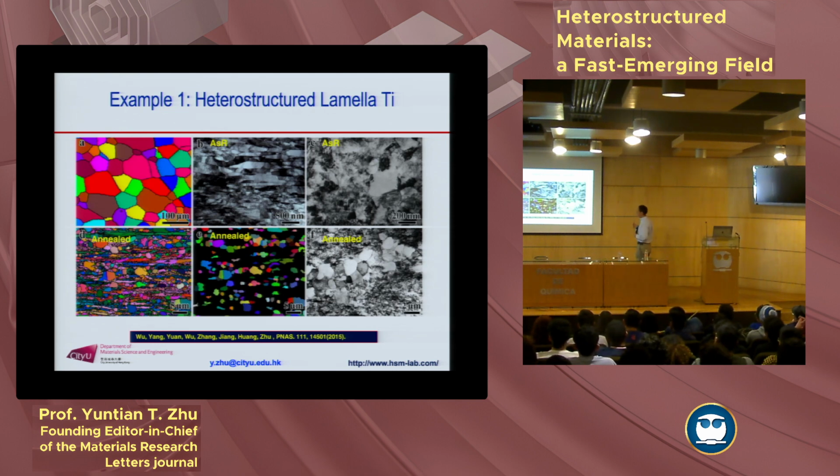This is the first paper. We studied this new field. We studied titanium with a coarse-grained structure, with a grain size of about 43 micrometers. After asymmetric rolling, you produce the ultrafine-grained structure. Then we know in the industry, after rolling, what's next? Recrystallization. When you do recrystallization, you want to produce, if you look at the textbook, a uniform grained microstructure.